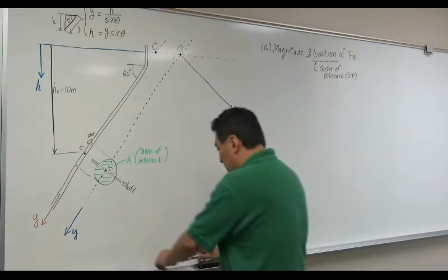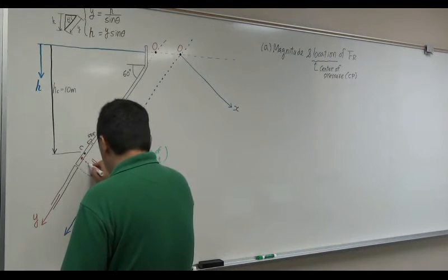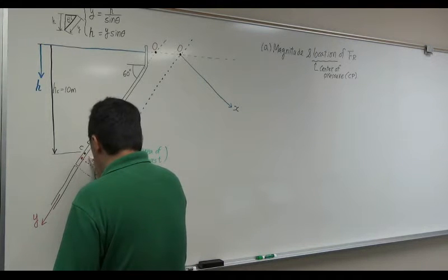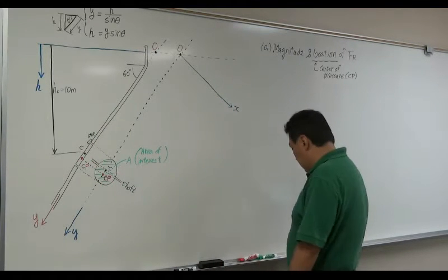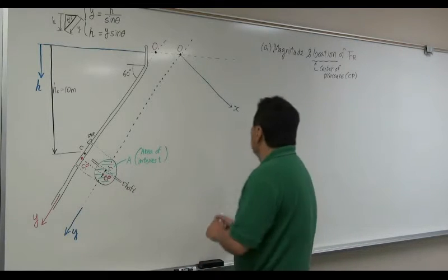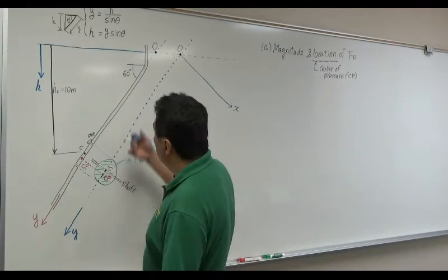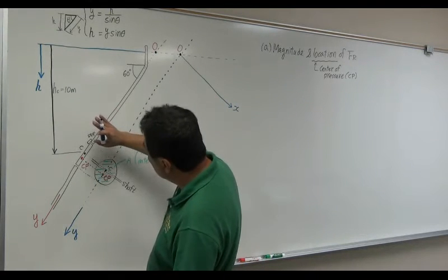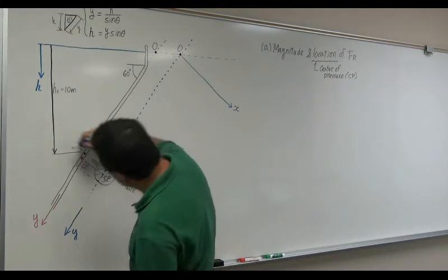So where is the center of pressure location? It's usually a little bit below the centroid. So this is the CP location, the center of pressure. And then this F1, the hydrostatic resultant force, because it's developed by the pressure on the surface, is always going to be in the direction perpendicular to the plane surface and acting through the center of pressure.